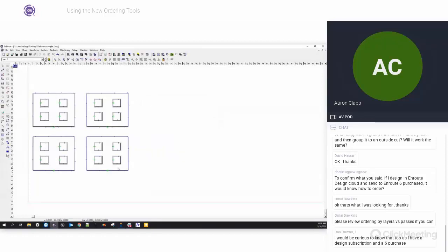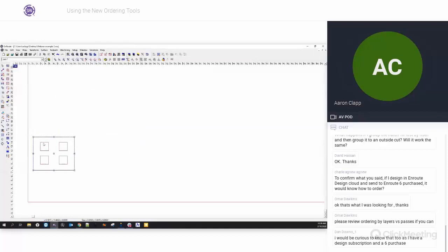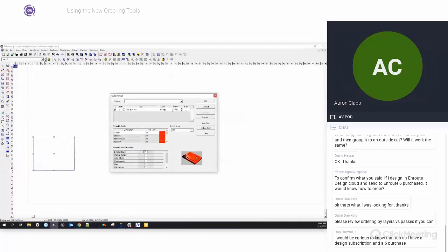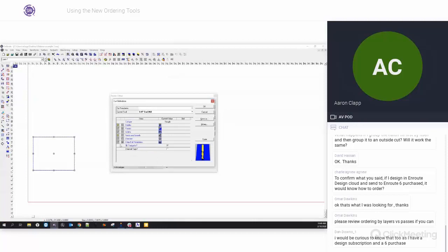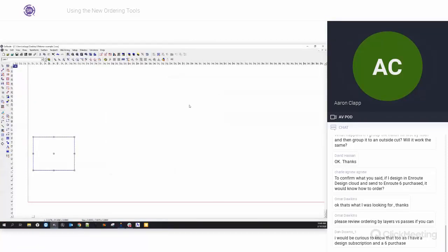In fact, let's modify our file just a little bit. Let's remove the toolpath. Let's just make this really simple and easy for us to do a little demo on this real quick. Oh, these are grouped. Need to ungroup those first. There we go. Okay, so I'm just going to delete these as well. I'm going to apply a routing offset on this. It's going to be 0.75 inches deep. I'm going to make sure that I have multiple passes. I do. Okay, and I'm going to make 2 copies.